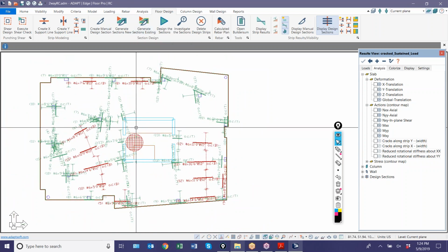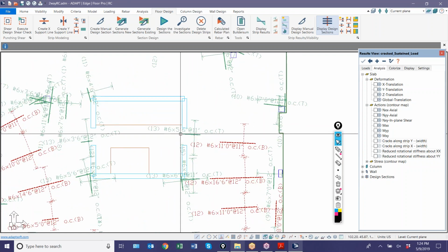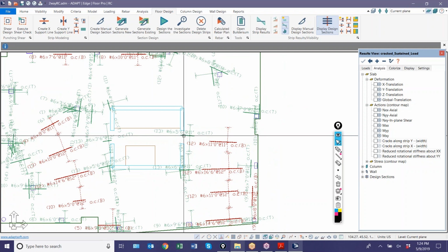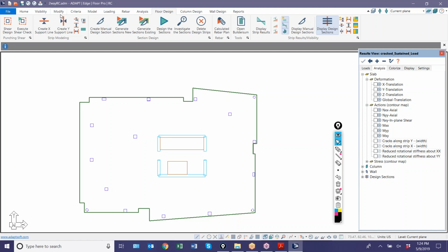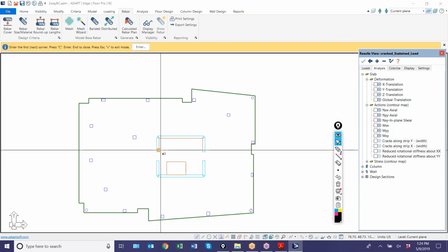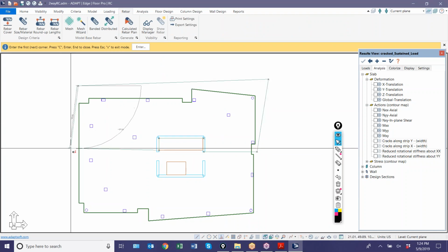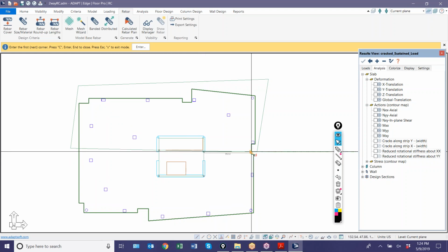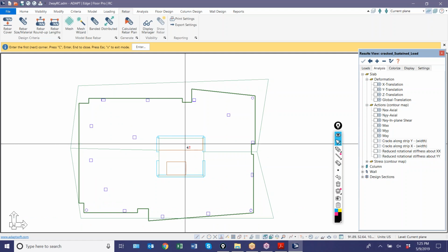And some of this rebar that creeps into here is really just based on some extension parameters in our algorithm for generating the layout. But in terms of the mesh reinforcement, instead of using the wizard, I could just create a mesh, and I would literally have to map the rebar. This is just like a polygon input. I would create a mesh maybe over here. I'm not going to place it right on the slab necessarily, and I would create a mesh in this region here. So you might create two mesh regions and nest them around the opening.